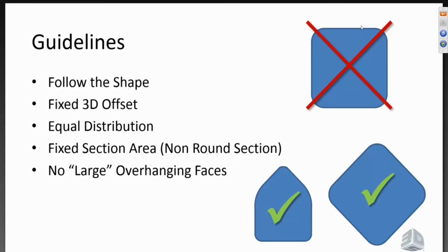When you think about the process of printing the core, basically, we're layering layer and layer down upon one another as we build up the steel on both sides of that water line. Well, what sits in between here is just powder. So as we get to the top, all we have to support the top when we lay that last layer across that closes the top of the water line is powder, and that's not enough. We're trying to stretch this all the way across with no support. Okay, so that's what we call an overhanging face. It's sticking out over a void with nothing but powder in it. What's there to support it? All right, that's an important thing to realize about the printing process.